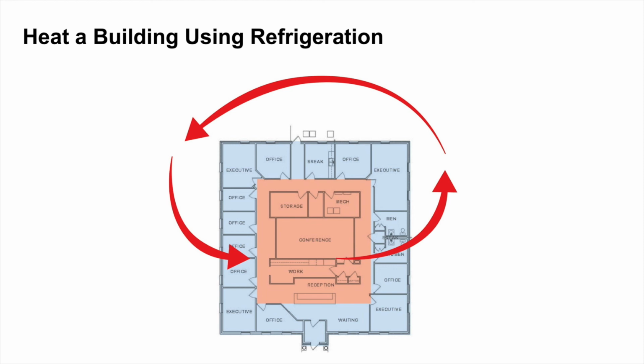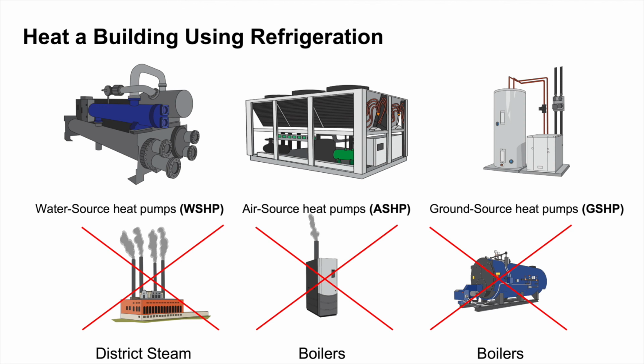So that's the theoretical concept we're talking about with building electrification. How are we actually going to do that? We do that with heat pumps, which is why we've been talking about heat pumps all morning. There are two ways you can apply heat pumps to commercial construction projects at this scale, in large centralized configurations. We had the example of the residential split unit, which is exactly the same technology, or you can scale this up to something much larger: centralized refrigeration machines, water source heat pumps, where the source of heat transfer is two different fluids, or air source heat pumps, where the source or sink of the heat transfer on one side of the refrigeration process is the ambient air. The air source heat pump is very similar to that split unit example with the house, all in one big package.